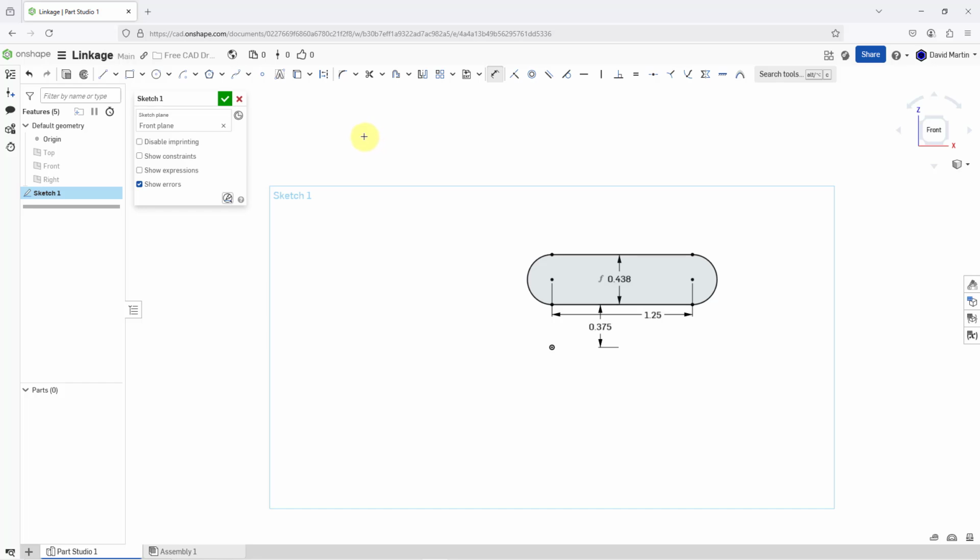And I need to have a center line to get the center of the circle right about here. So I'm going to go right to construction mode, and let's make a horizontal line, and I'm going to exaggerate its length and just drag it out about this big. Again, it's just going to be some reference geometry, and I will hit the escape key.